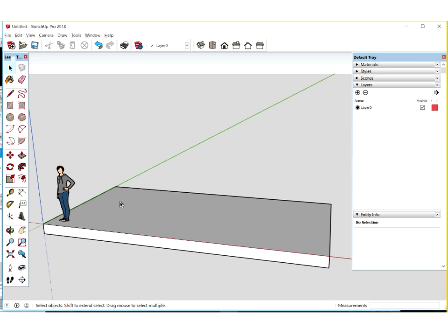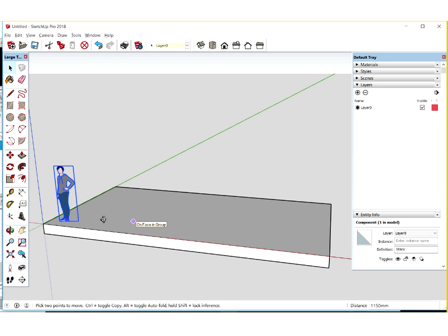Right, next thing we're going to do, we looked in the last SketchUp workshop at a couple of different ways to build walls. I'm just using my selection arrow there to click on the human figure. This one's Stacy. I know they've just introduced some new characters in SketchUp to keep it fresh. When you're moving anything, think about your starting point. I always try and reference one of my surfaces as a starting point, and I'll be careful where I'm moving her there. So both the starting point and the end point there were on that face.